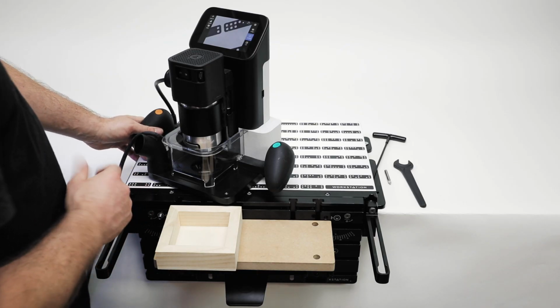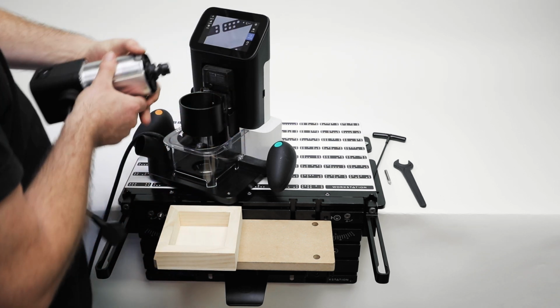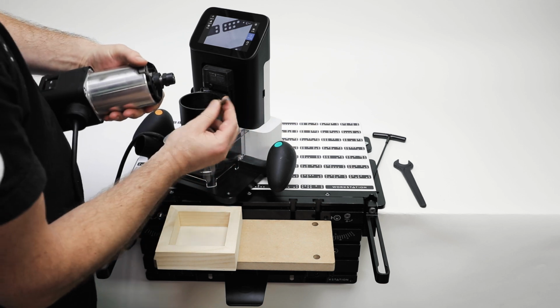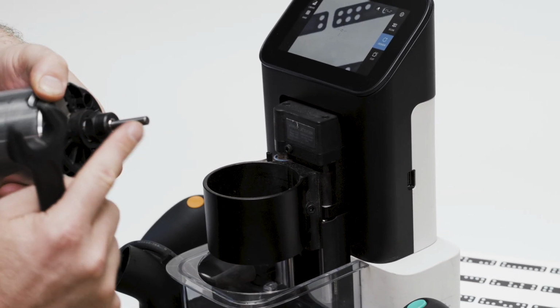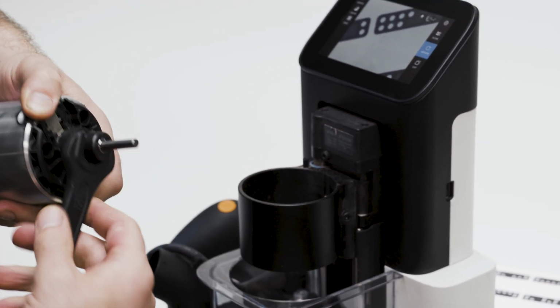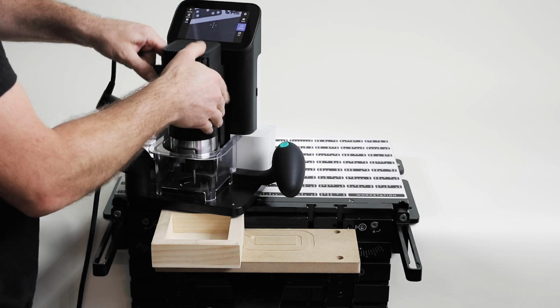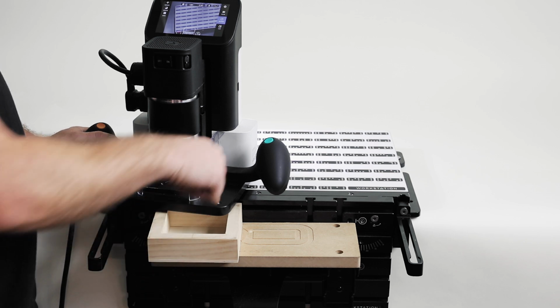First things first, we'll place an engraving bit inside the spindle collet upside down so that the cylindrical shank is exposed. And we'll use that perfectly 1/4-inch cylinder to do our precision probing. We'll take an engraving cutter, put it in upside down, and tighten it up. So we'll go through the motions of creating some grids.